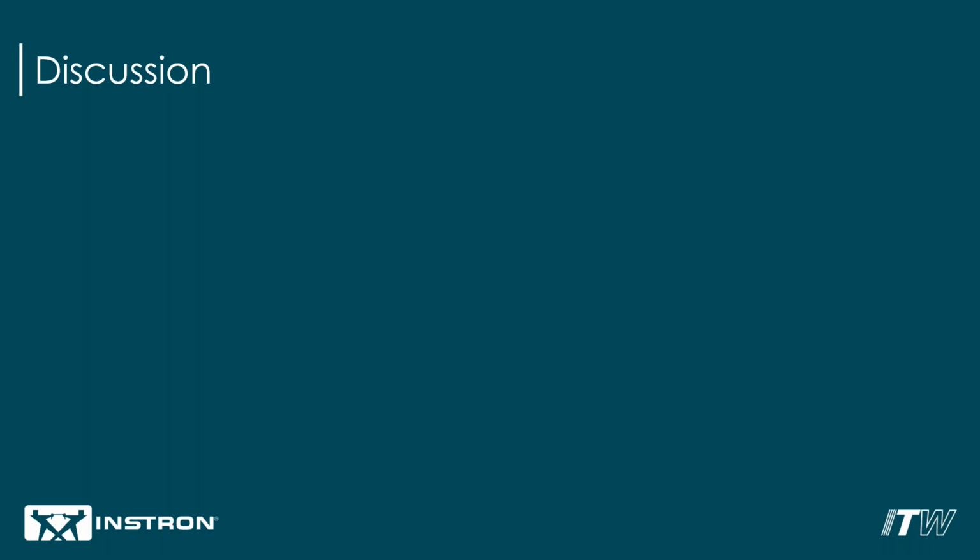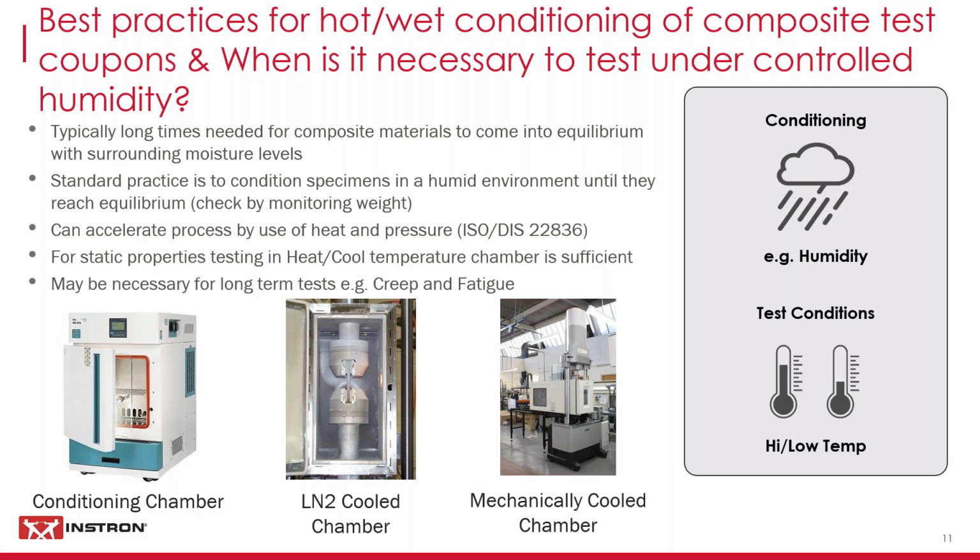Yes, they were. In the previous image, in the LN2 cool chamber, yes, those are hydraulically actuated grips, but the hydraulics are not inside the chamber. The pistons are actually located outside of the chamber, and then you have two coaxial sleeves and an inner rod that actually are activating the grip head. You need to do that in order to have reliable operation. You don't really want to be putting hydraulics inside the chamber.